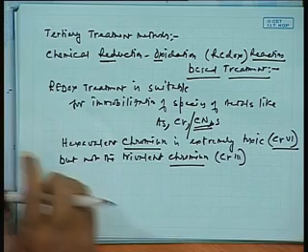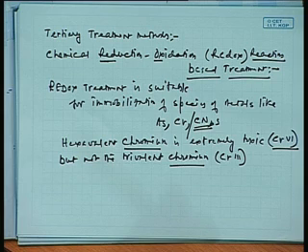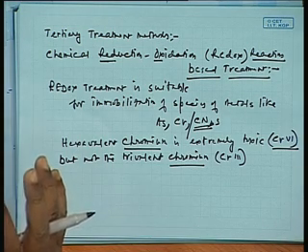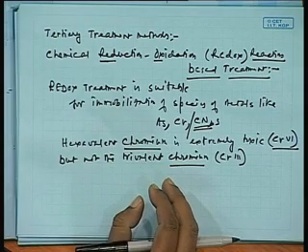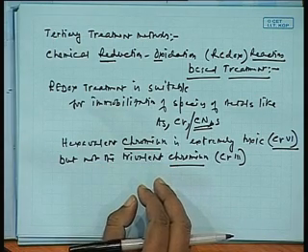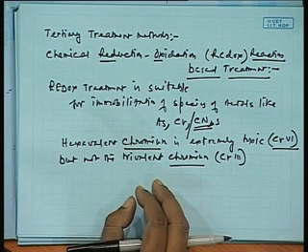What we try to do here is not precipitate chromium. We may like to convert hexavalent chromium into trivalent chromium, so that it would be largely immobilized. That is, it will not move from one place to another. And secondly, in any digestive tract or any other passages through which it passes, it will not be reactive. It would remain as it is and completely pass.